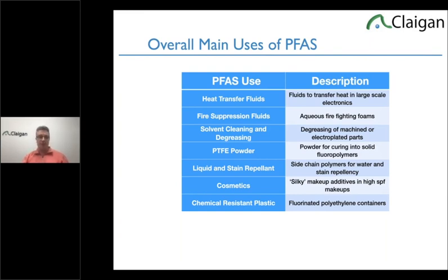And one of the problems is the replacements for PFASs often are really poor at the job. Silicone can repel water fairly well, but it absorbs oil. So it absorbs stains and stinks, and it's just a bad idea. Fluoropolymers are also much less reactive and a lot safer.